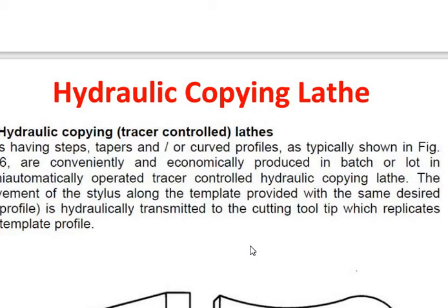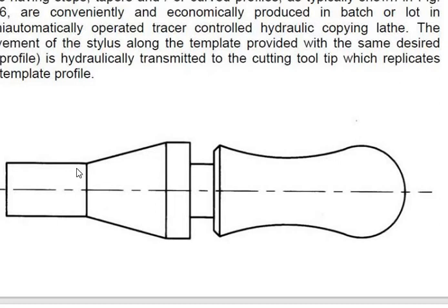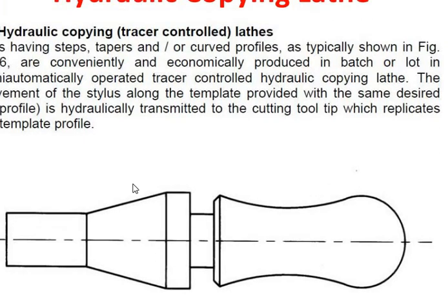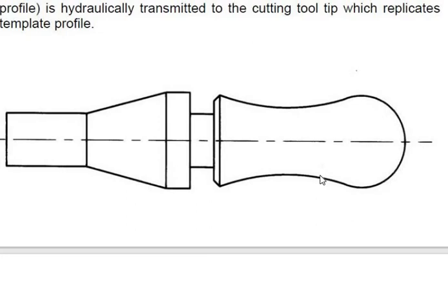Jobs having steps, taper, or curved profiles, typically as shown in the figure, are conveniently and economically produced in batch or lot in a semi-automatically operated tracer controlled or hydraulic copying lathe. The movement of the stylus along the template provided with the same desired job profile is hydraulically transmitted to the cutting tool tip, which replicates the template profile.